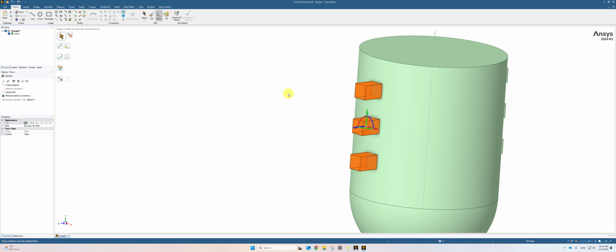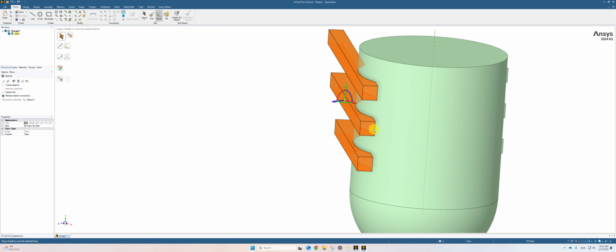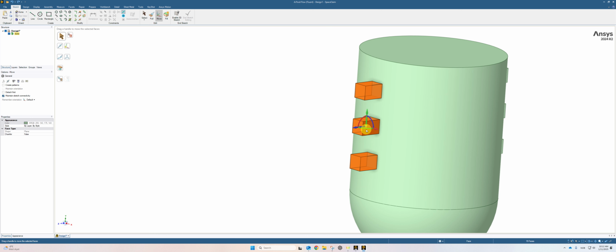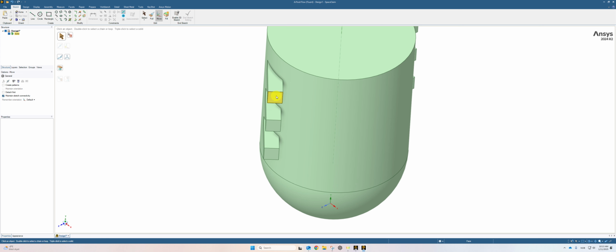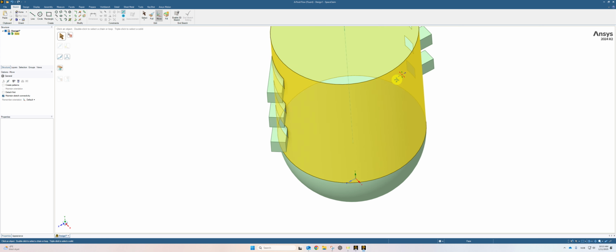move and I would like to rotate it around this y-axis for let's say 55 degrees, or actually not 55 but 50. Okay, and now you can see that the water is going to be injected in this direction and then it's going to circulate that way. Therefore I have to repeat the same for the other side.